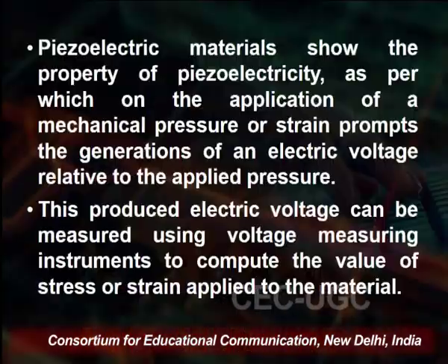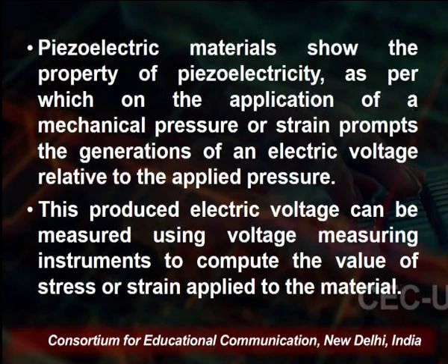When mechanical pressure or strain prompts the generation of electric voltage relative to the applied pressure on the material, that material is known as piezoelectric material. This produced electric voltage can be measured using a voltage measuring instrument to compute the value of the stress or strain applied to the material. That means we can see how much stress we are giving and how much electricity is generated through these